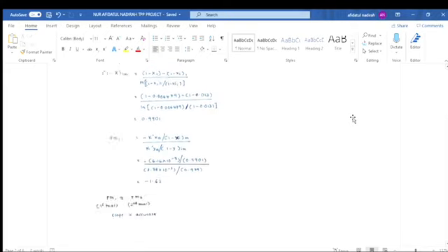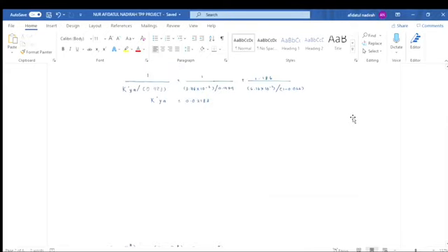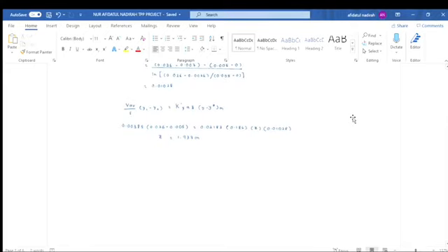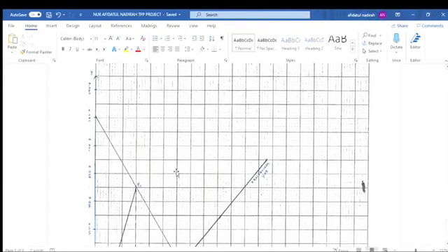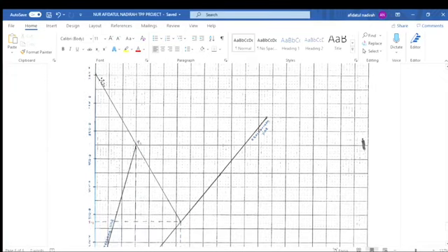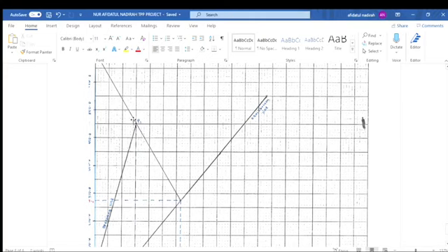So I will show you how to find the values of xi1 and yi1 in the graph. We already know that the y-intercept is equal to 0.0364. So we have to drag this point to the operating line, and we have to use the same slope to drag it to the equilibrium line.